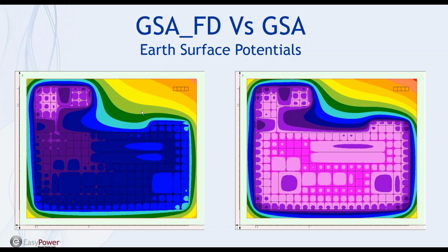We know this is possible in some cases, in particular if the grid size, frequency and soil conductivity are lower than a given limit. So many times this simplification is acceptable, but it is not easy to know exactly when the equipotential assumption is valid. In this regard, the results of a parametric study we did, taking into account a square and well-matched grid of copper conductors, have been described in the introduction, as you have previously seen.